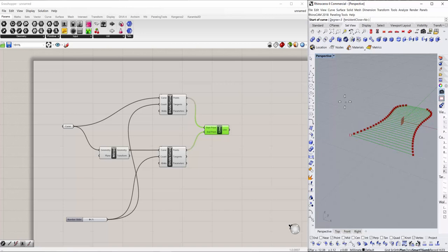Now in the next step we will be evaluating these curves, because we want to create a vertical height, as we want to rotate this curve and make a surface. So we need a height so that we can create an arc from these 3 points, and then we can loft that surface.